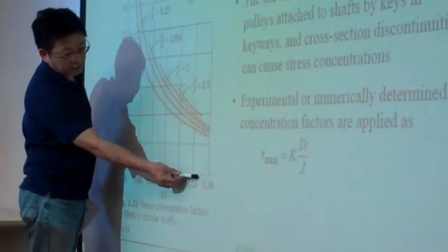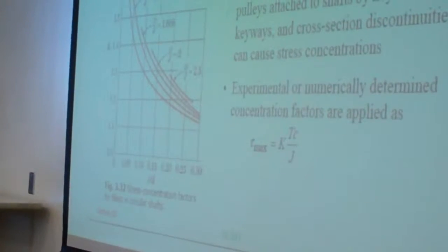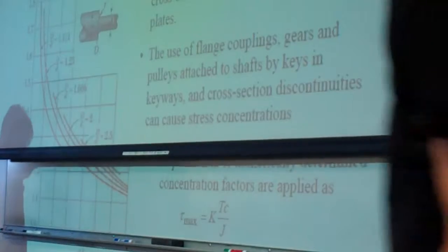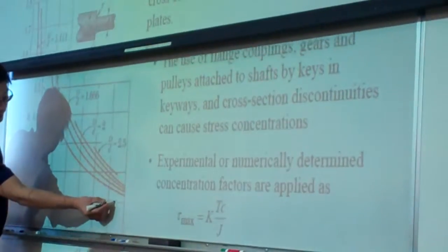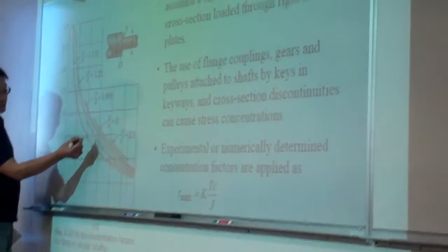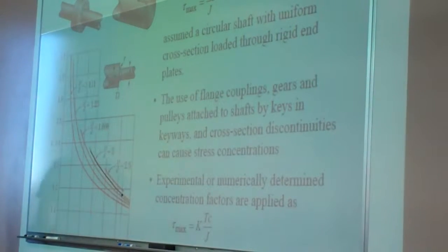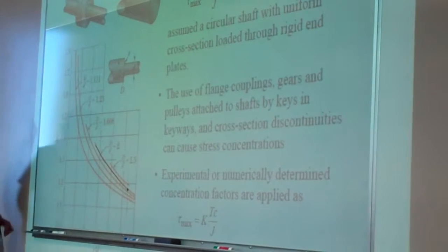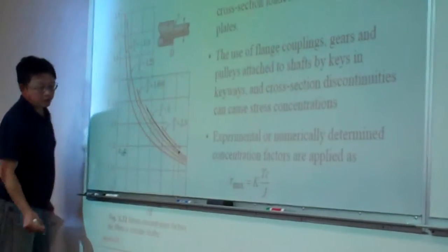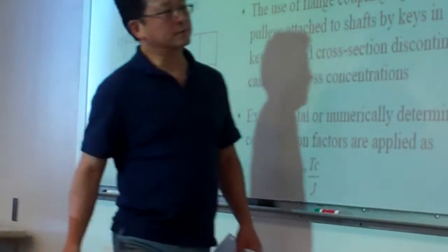One-third beyond, so that should go to here. And then we get the value for 2. This curve corresponds to this value, so this is a point. The K value corresponding to that point, we can estimate, is about 1.18. Estimation will be good. So the K value is 1.18. We take down this value here.